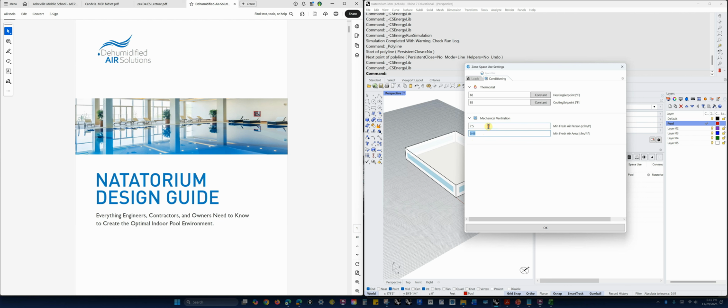So the way this works is you have to have fresh air ventilation for the number of people because they have to breathe, but you also need to have ventilation based on the size of the building and for different uses, how much you need to flush it out in terms of if there's off-gassing and other pollutants inside. So there's two different numbers, and this is very high, like 0.06 would be what we were doing as a baseline for NYC.